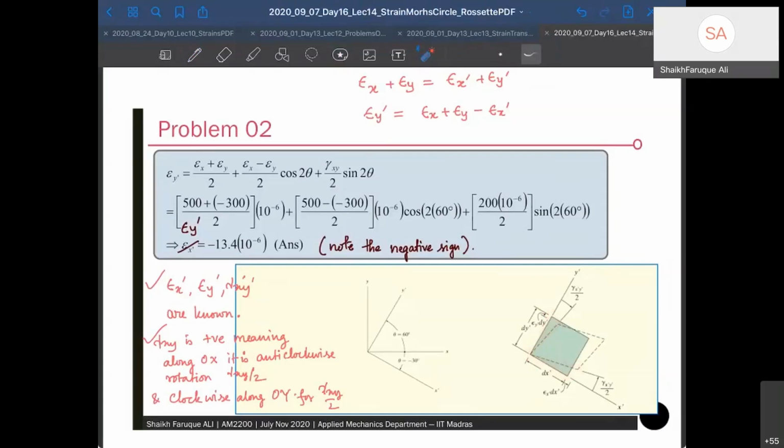So there is a positive value, so there is an elongation here. There is a negative value in epsilon y. You can see the negative value here. So it's a compression a little bit. So this is going to become this, and then you have to draw parallel lines, right? Just parallel lines, and then you get this point. So that's your deformed configuration in a rotated coordinate axis or a transformed coordinate axis.